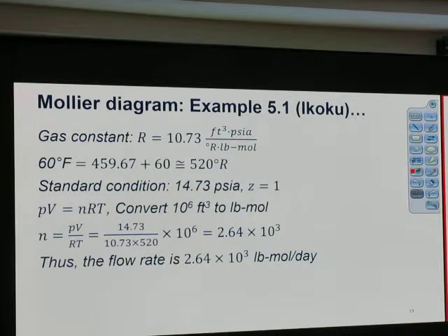We have constant mass flow rate. Jayanti, can you go restart the camera? Or you did that already? Okay, the mass flow rate through the compressor is constant. If a certain stage is hotter than usual, this means we require more cooling for that particular stage.